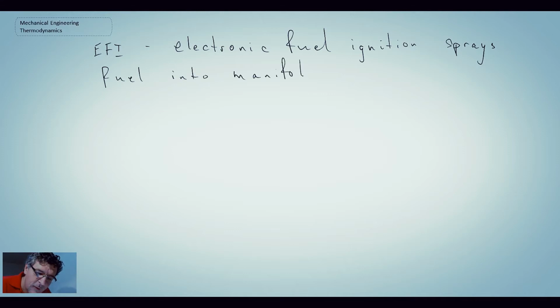If you look at older engines, here what we have is a fuel injector sprays fuel into the inlet manifold, which is where the air is coming into the engine. It goes through an air cleaner first to get all the particulate and dust and particles out. But then it'll be flowing into the engine. The fuel injector will spray fuel in. That then flows into your cylinder, which would then be compressed and combust.